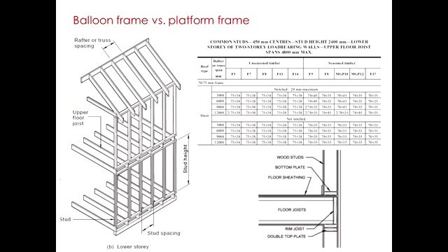The studs were broken down into two parts, ground floor and first floor. So the two advantages are shorter products to handle, below 3 meters, very easy to transport, very easy to place, and they're safer. And there is another advantage.